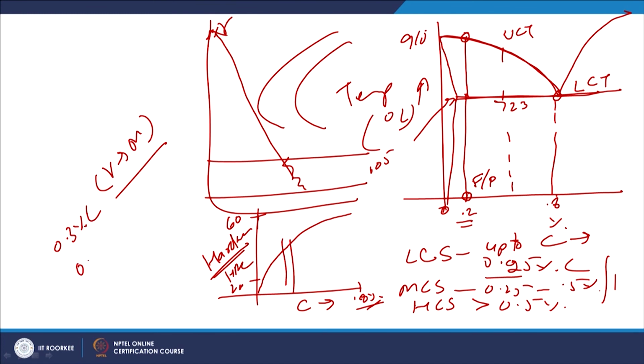But if the carbon content in the steel is like 0.6%, then this kind of transformation will lead to high hardness. So, despite the martensitic transformation we do not get very high hardness if the carbon content is low. What it suggests is that not all types of steels can be subjected to transformation hardening for improvement of the surface properties.